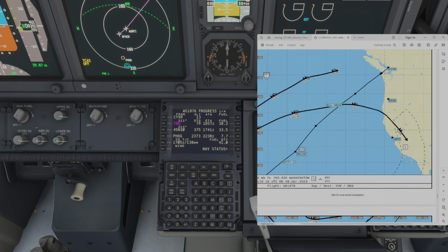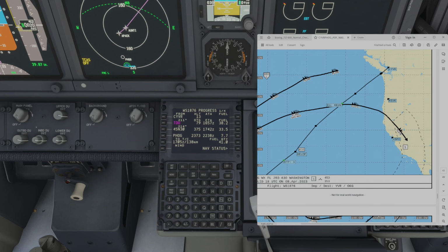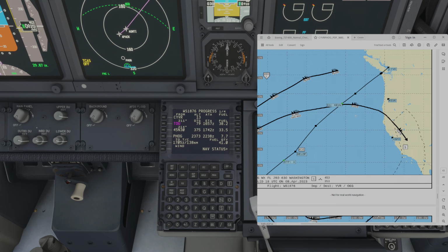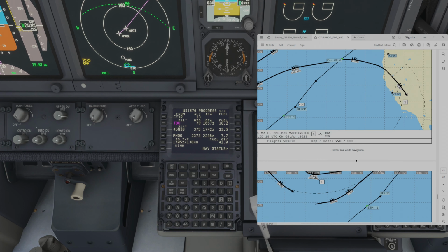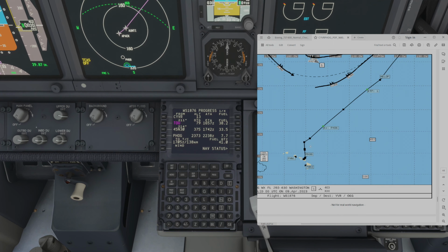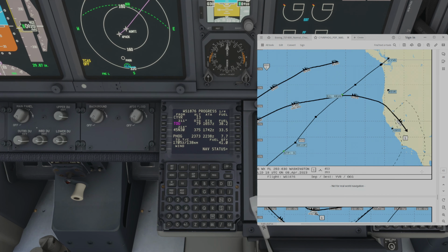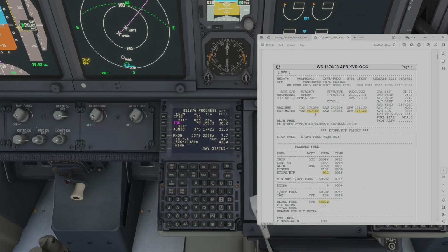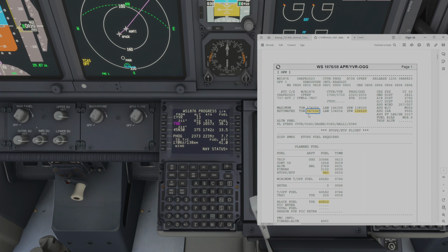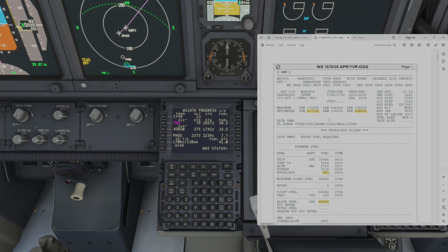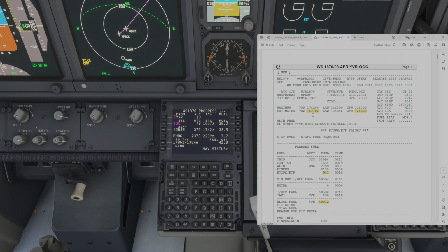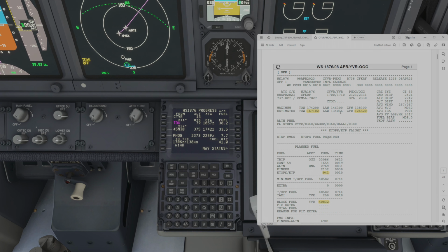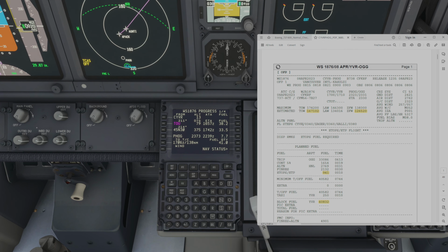And this is our route here. We are going to be passing through a jet stream, flight level 370. There might be a few turbulent chops there. And as we continue on, it should be smooth weather. Takeoff weight 167,102. We are going to be above our maximum landing weight. Alright, so we'll drop that off here.